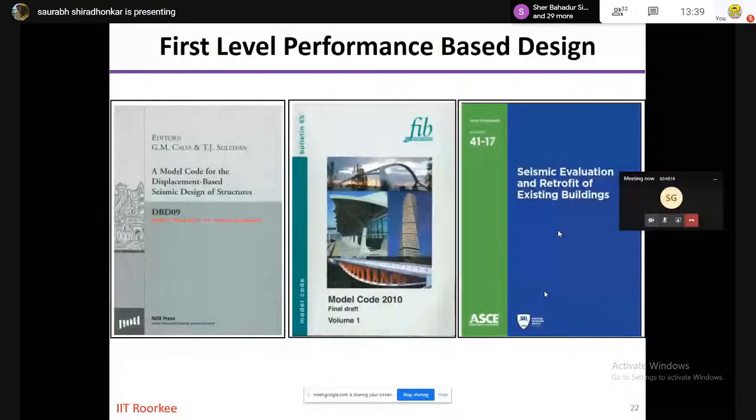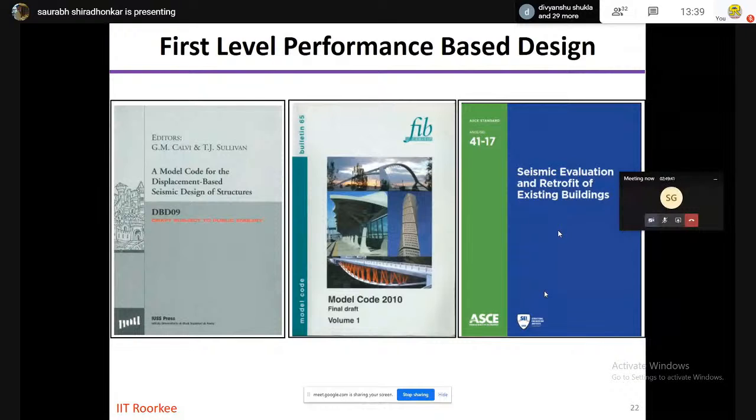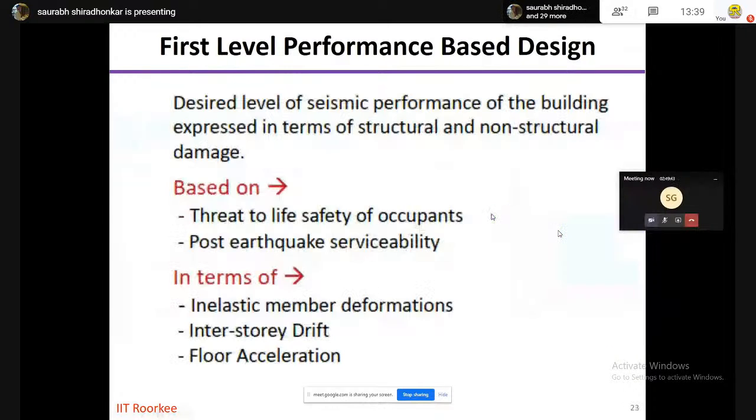acceleration which is imparted by the ground motion, the forces are also proportionate to the stiffness times the displacement. So the displacement caused by the earthquake ground motion, the relative displacement caused by the earthquake ground motion, is a very peculiar characteristic for designing of the buildings. So in these methods, again, the formulation is changed from force based to displacement based.